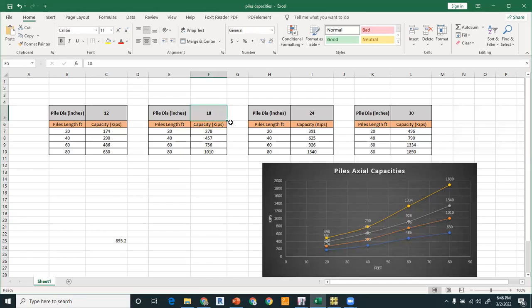For example, if you want to work with the 15 inches or 21 inches dia pile, then you have to make your own bolt, or the bolt size for the boring of the pile, and it will be much costlier. So you have to work with the available boring molds, so it will be very easy from the construction point of view.